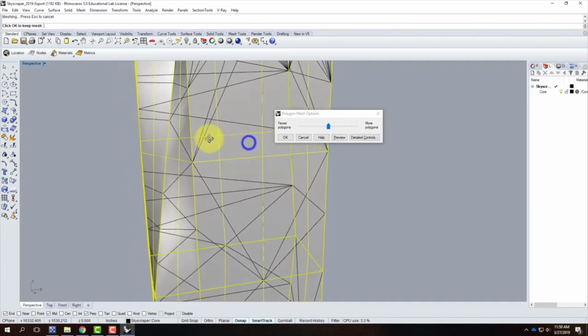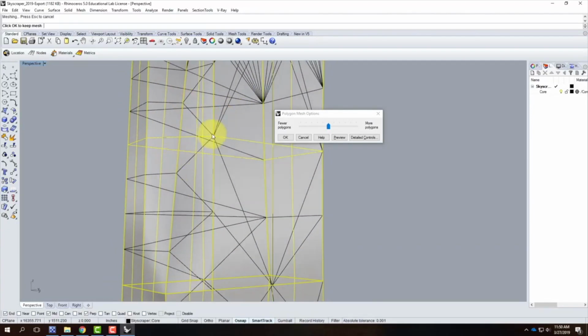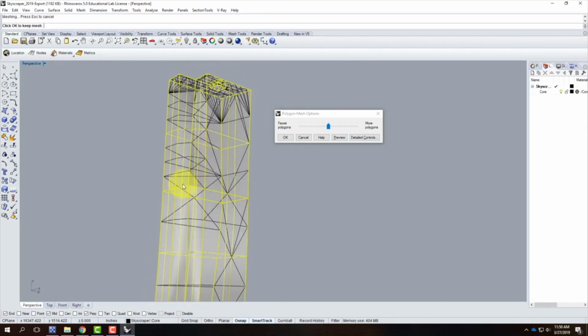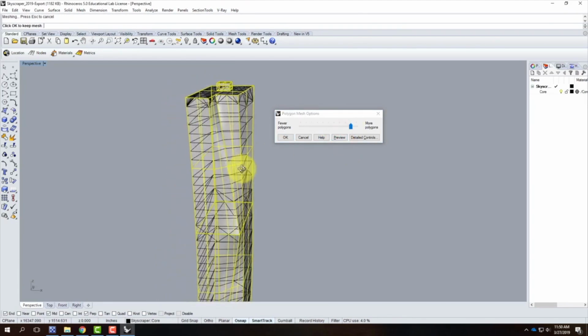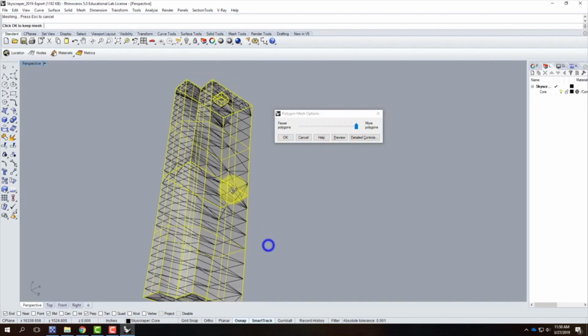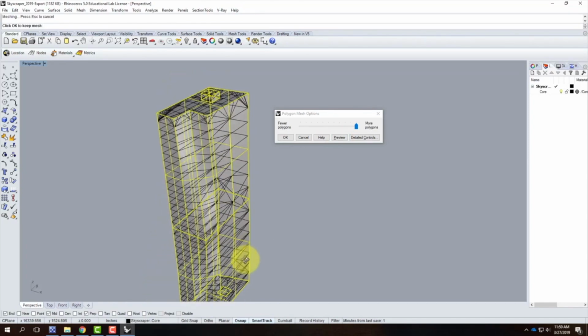Now recognize that this is making some facets, some triangular facets out of the curving smooth surfaces. So you can see on the front here that it's kind of simplifying the curve that I have, that inverted curve. If I drag this over and hit preview again, you'll see that it's making smaller sections out of it. And you can actually see it on this. I can pass this around again. A lot of you have seen this already. You can see the facets or the triangles on the surface. It's not as smooth as it otherwise would be. So the higher I make this, the more little facets there are going to be. Once I have it set, I'll go ahead and say OK.